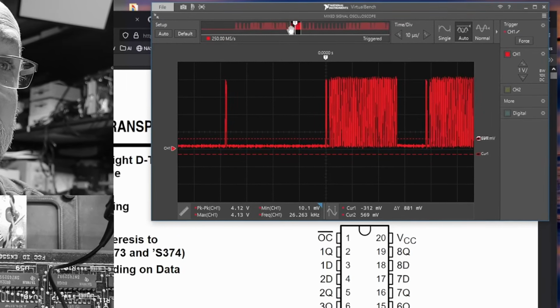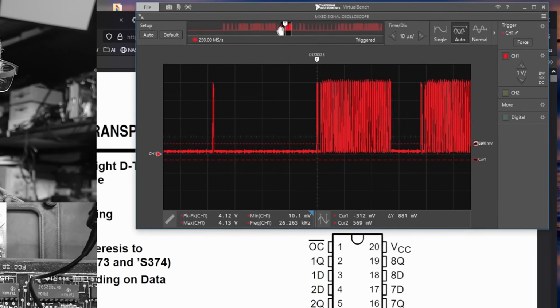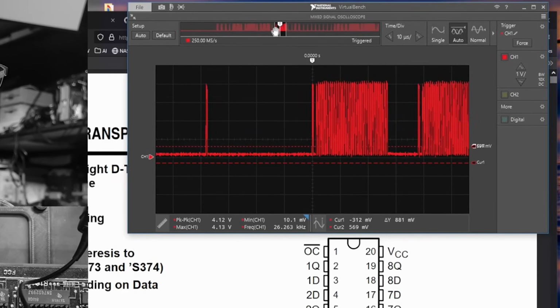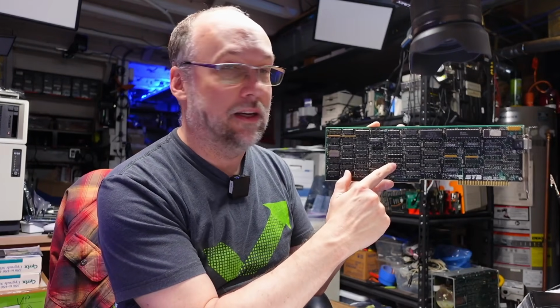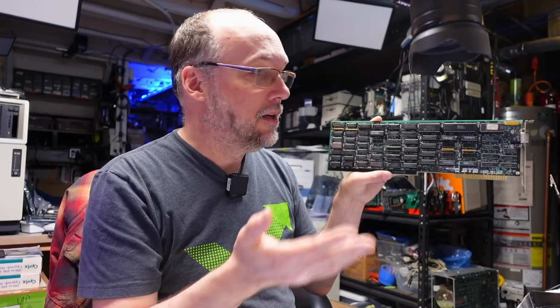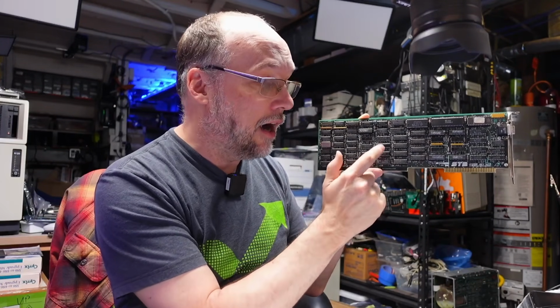And I think if I had had a text mode enabled when I was testing this chip, we would have seen much more of the bad signal, which I think I might have caught in that initial phase of testing. Now I did get there in the end, but I feel that that was kind of luck, and that just happened to be because that weird clock signal leaking onto here was causing the output of this one to always look like it was down at ground, which I just assumed was a fault, when the reality was it wasn't. It was just that clock signal leaking in and causing that to always look like it was there at ground.